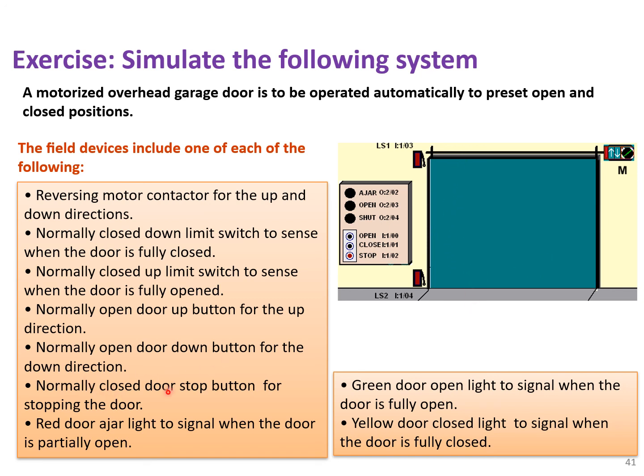And you see the difference between the stop buttons and, let's say, start buttons is that usually stop buttons are normally closed, yes, but the two other ones are normally open. So it means that in our programming, we could just use a normal contact, and that normal contact will stay true until we press that contact and will basically become false.